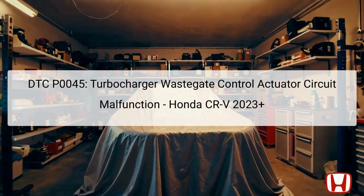The diagnostic trouble code P0045 signifies a malfunction within the turbocharger wastegate control actuator circuit, specifically concerning the control actuator's operation or response. In vehicles like the Honda CR-V 2023 and newer, the turbocharger plays a vital role in optimizing engine performance and fuel efficiency by regulating the flow of exhaust gases.